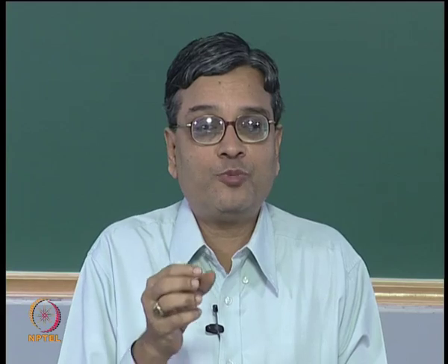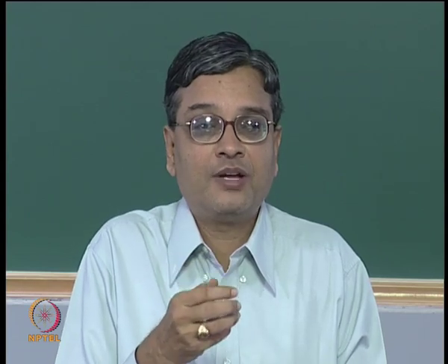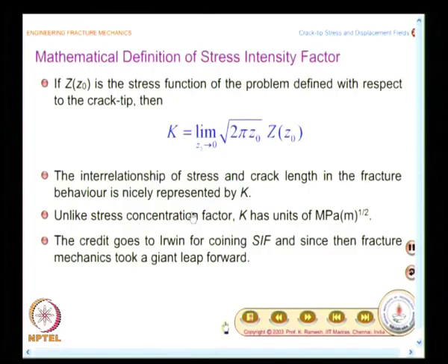So, this is again an advantage from Westergaard's approach. He was able to provide analytical expression for a variety of problems. So, people felt that they are able to apply fracture mechanics to certain situations in practice. And I have already mentioned that K has units of MPa root meter, which is quite different from our knowledge of stress concentration factor, which was just a number. In the case of stress intensity factor, you have very funny units.